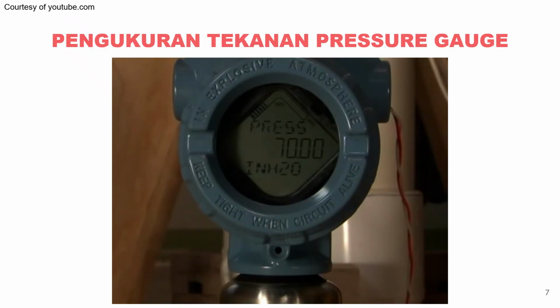Now see, with just that little bit of air, the pressure reading changed pretty dramatically. Now it's leaking out. But you can see that had an obvious effect on the reading. If you were using that for the reading, you might say, wow, how come the level changed that abruptly? When in fact it didn't change at all.